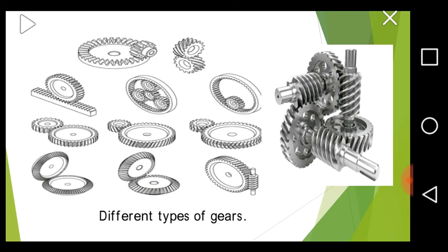It's expressed both for rotary speed and for torque. So the constancy of the gear ratio means that given the same input, the device or system constantly provides the same output speed and torque. On the other hand, devices and systems which employ non-circular gear experience variable speed and torque ratios. Variable speed and torque enables non-circular gear to fulfill special irregular motion requirements.